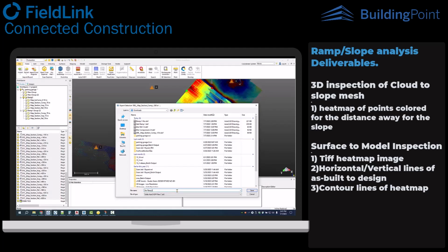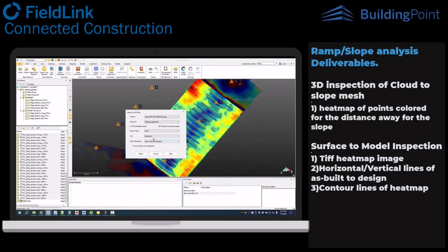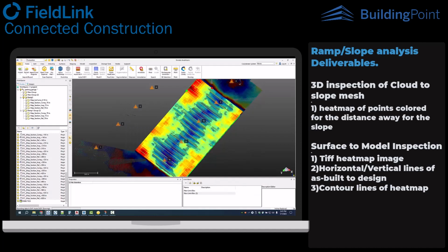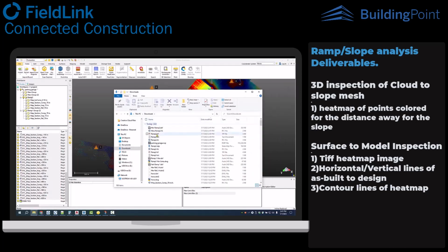Horizontal ramp 2. And so set this, because DXFs aren't defined by units. Usually I do inches because that's a pretty standard thing to see within most AutoCAD environments. So with that, I have my whole horizontal DXF. What I'll do is bring this into Connect to show you that deliverable. Again, you could bring the same thing into AutoCAD or Revit, as well as take those screenshots and measurements, but generally this is going to give you a good idea.